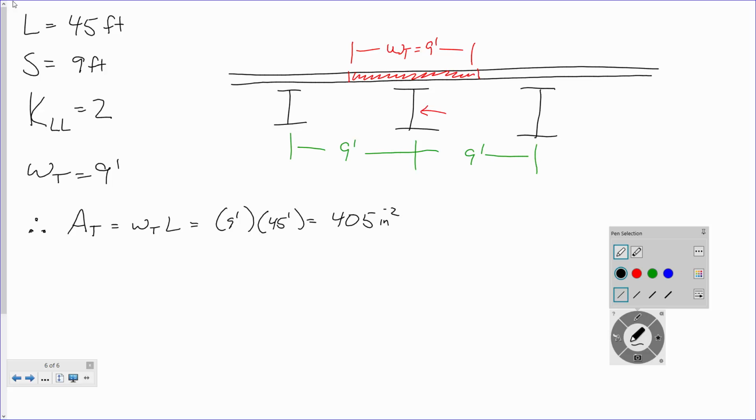Okay, so what if we had a section? This room, hypothetically, is perfectly square, and I have a row of desks that nobody goes under, and I know that's attributed to dead load, right? Desks are related to occupancy. That's live load, because live load is occupancy. That's what the building is being used for. So if this is being used as a classroom, then the desks count.